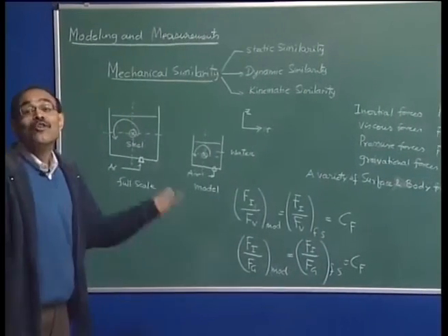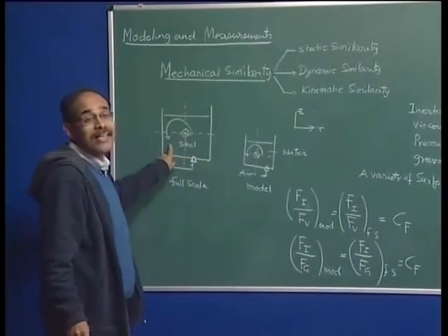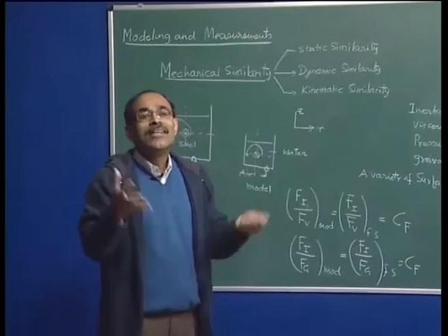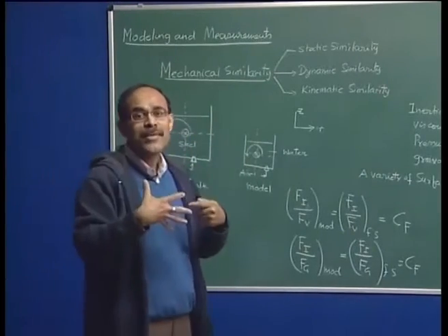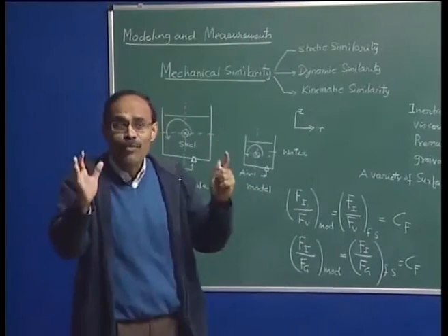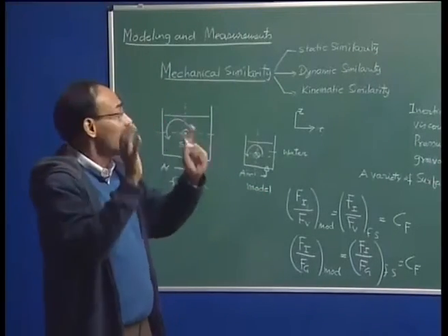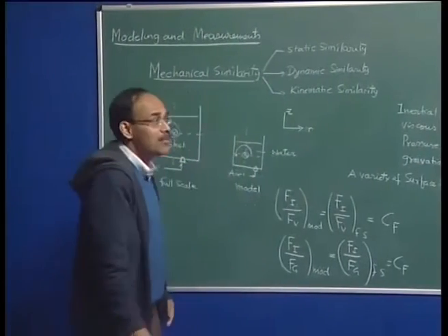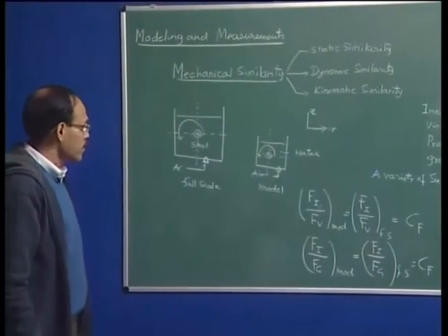If you say, sir, I do not know the equations applicable to the system, in that case we have to carry out an elaborate analysis, dimensional analysis, carry out some experiment, and then find out which are the meaningful forces. It is only when we know what the meaningful forces acting in the system are that we can proceed to develop the dynamic similarity criteria.